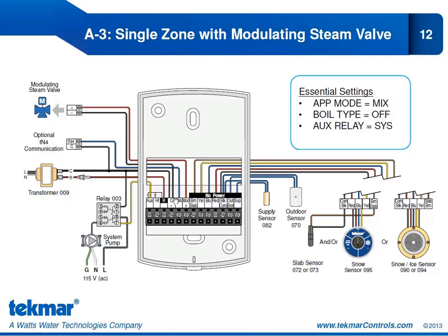We've also shown here the TN4 and C connection for an optional TechNet device. So we could connect to a gateway or perhaps a user switch, whatever we'd like to. We've shown it as optional so you know that this is a possibility for this application. We're using our modulating output, plus and minus, to operate the modulating steam valve.